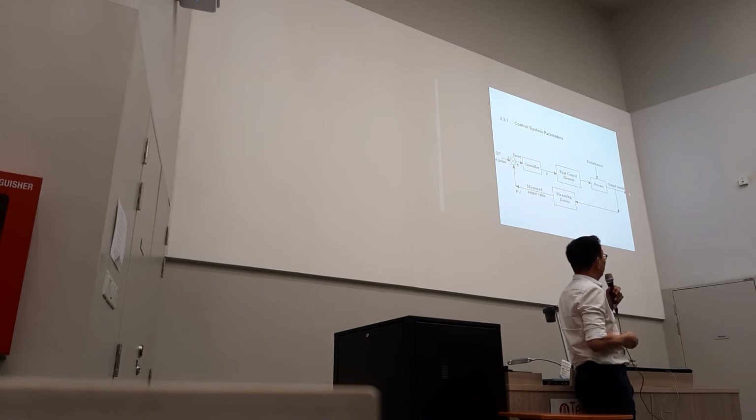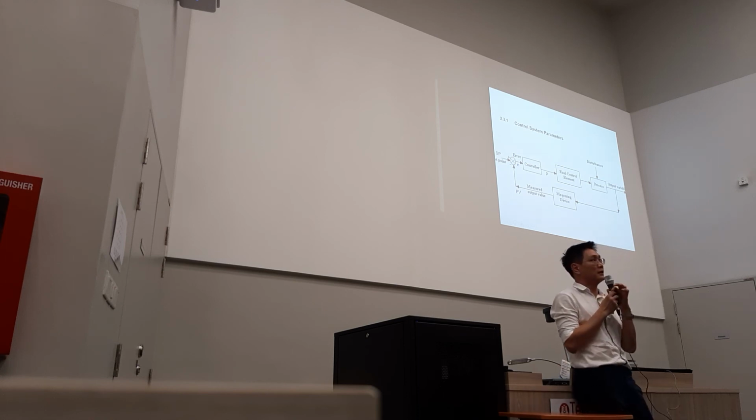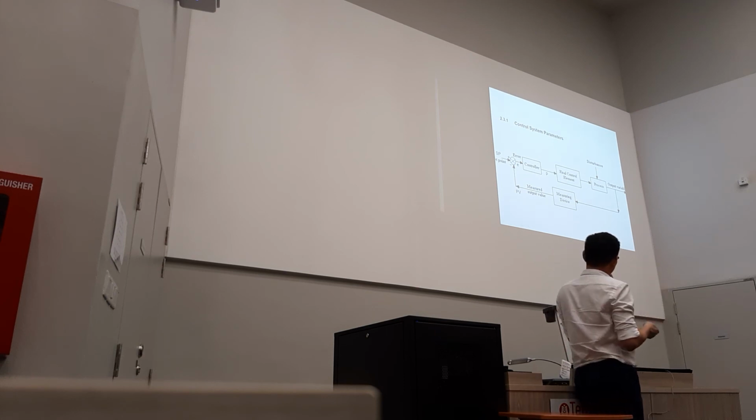Alright? This is what we learned in topic 1, right? How to reach this is to start from the process. Disturbance comes in, we have an output variable, right? And the output we normally measure with a measuring device. These are the instruments that we normally use, like temperature, pH, pressure, or flow rate. So we measure something, and then we have a measured output. What is PV here?